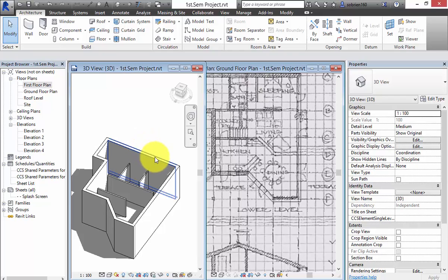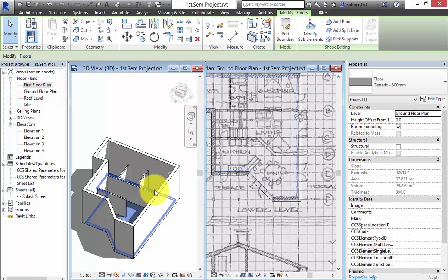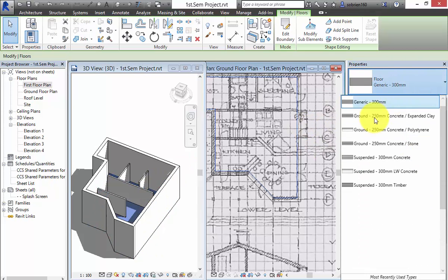So the easy way to do it is we can go into the 3D view, and if I just let the cursor sit on the edge of the floor here, I can use the tab key until it selects the floor. And you can see at the bottom, it's showing us that it's selected floor. Whoops, now I've deselected it. Let's try that again. Then I can click it. Now we've selected the floor here, with all the different things we can do with floors and so on.